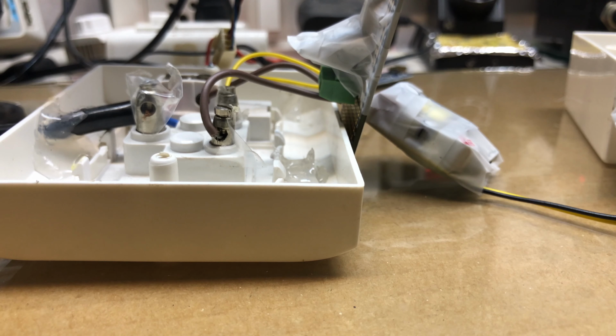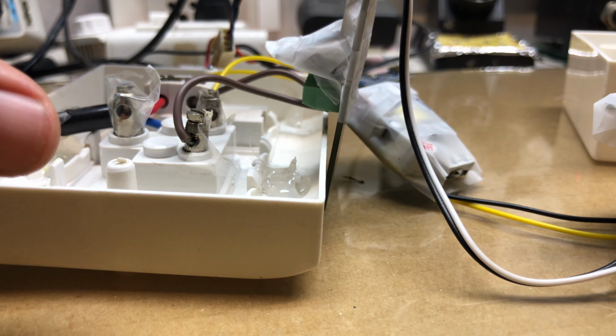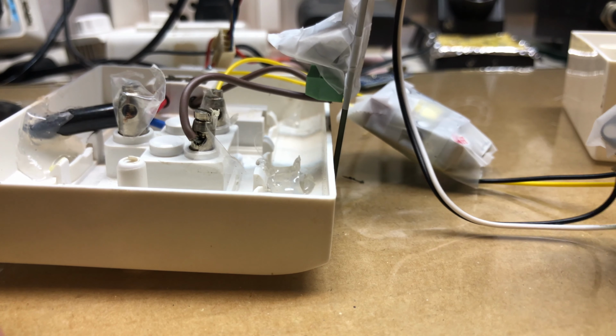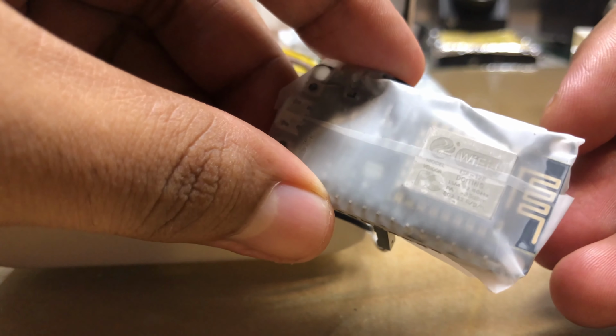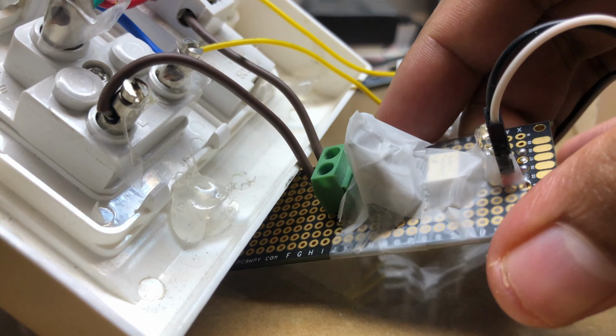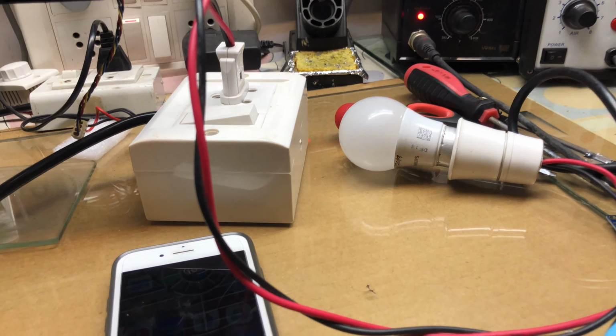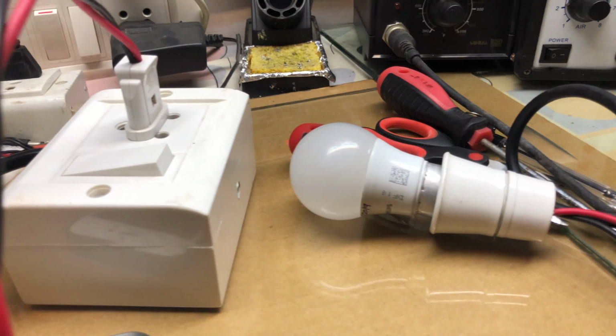Once you've connected the USB power supply to the NodeMCU, make sure that the GPIO turns on and off by sending it those HTTP commands. Next thing you should do, once you've confirmed that the GPIO changes states based on those HTTP requests, you need to insulate all the modules. Make sure that none of the mains voltage parts are exposed. So I've put everything together and we can test this out.